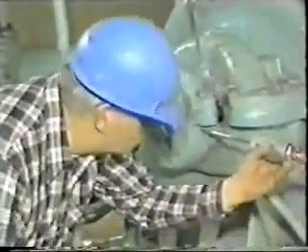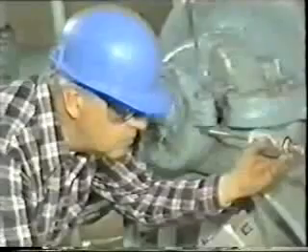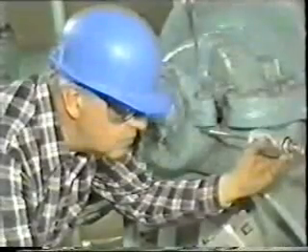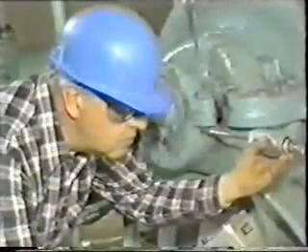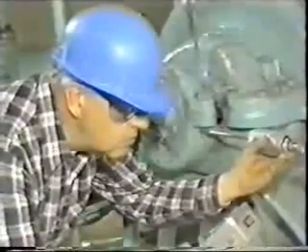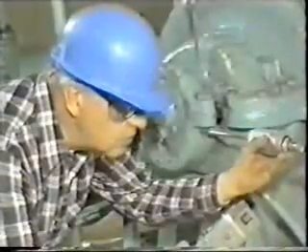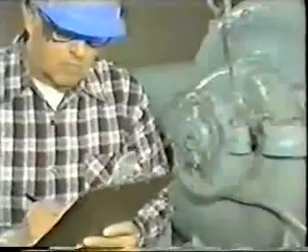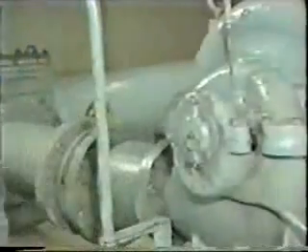When the probe is placed on the side of the housing, it measures horizontal vibrations. Make sure you place the probe as close to perpendicular to the housing as possible. Again, he'll check these readings against the normal range for this pump. Be sure to hold the probe steady long enough to get an accurate reading.